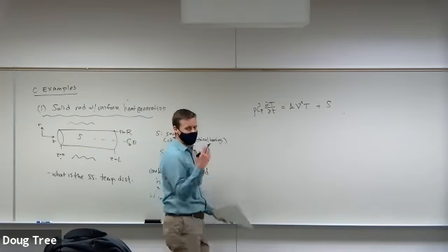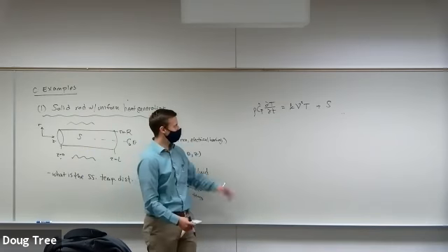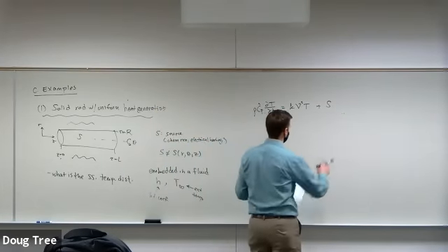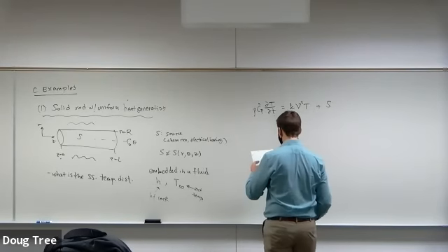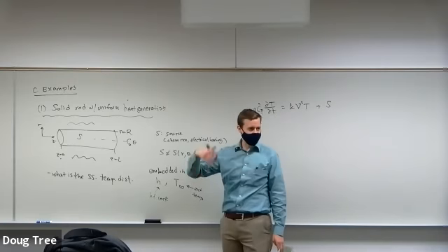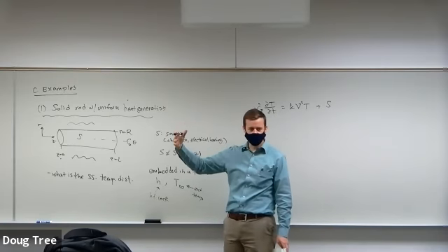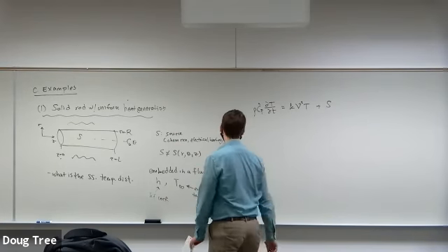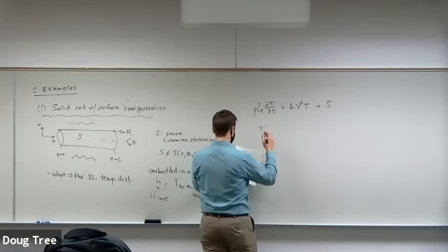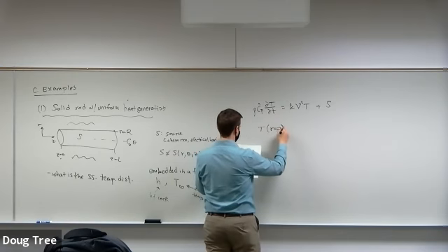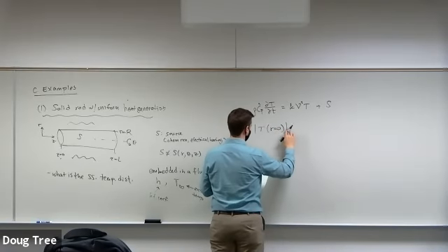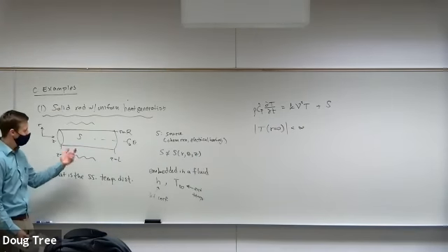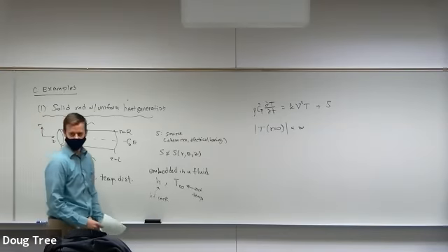Okay, so then we need boundary conditions. In order to be able to solve this problem, we have our governing equation. That's not enough. We need to know what the boundary conditions are to be able to solve this. And if they were transient, we'd also need to know initial conditions. So what are our boundary conditions? Well, we talked about these a while back when we talked about solving the energy or the shell balance problems. We talked about all the different kinds of boundary conditions. The ones that are useful here: we say that the temperature is finite in the center. Often when we have these cylindrical problems, that's one that comes to mind. We saw that with pipe flow.